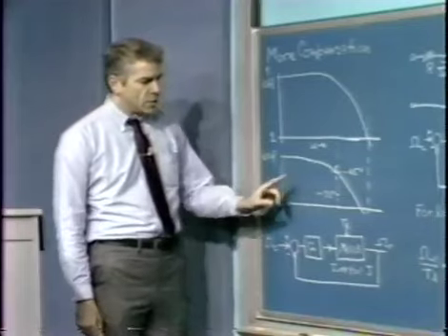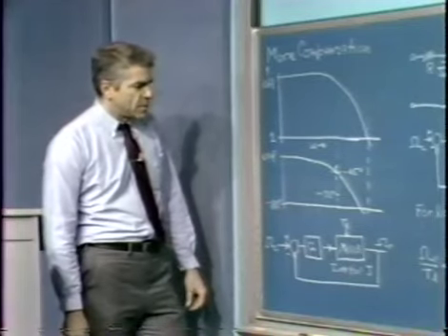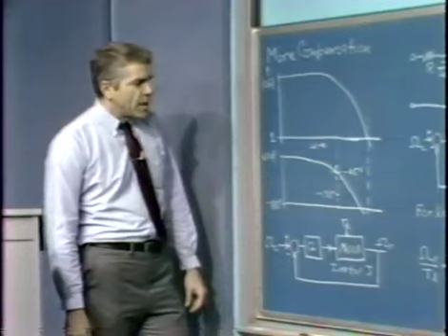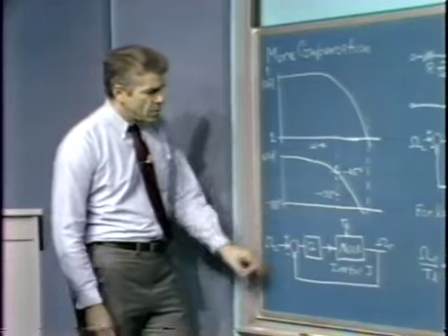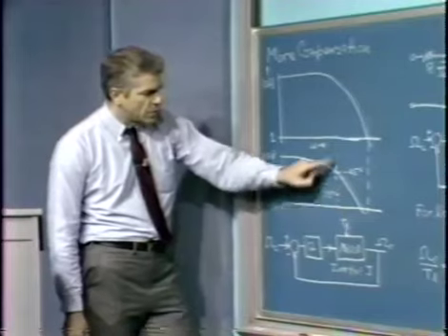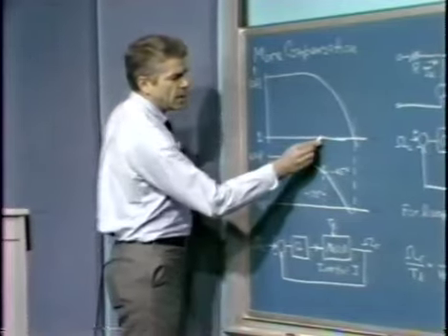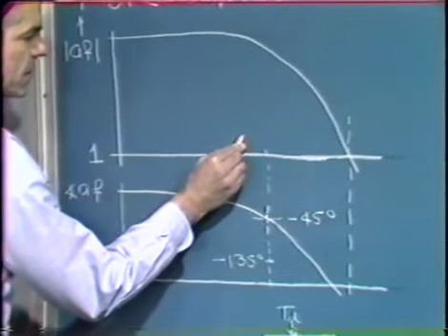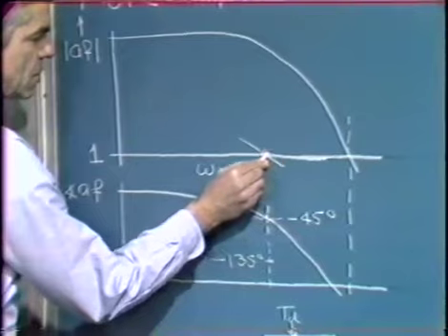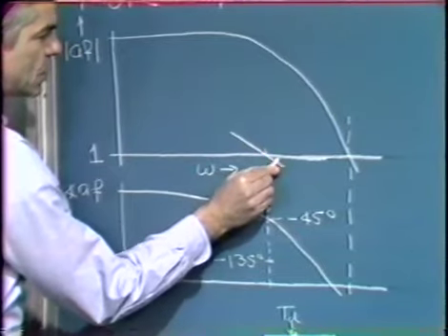All we do, assuming the physical constraints of the system allow that, is to somehow add energy storage to the system. And let's suppose, as we indicated, we'd like to cross over at this frequency. And that tells us that we'd like to have a single pole roll off like so in the vicinity of crossover.